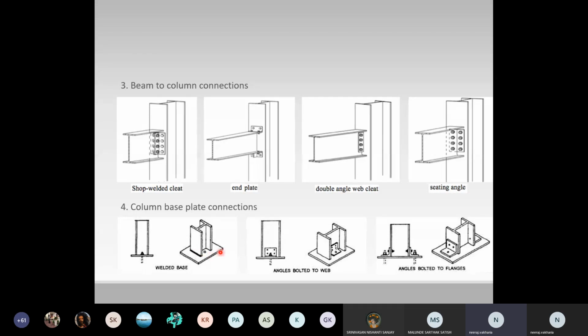Again, even the slightest difference in the level of this plate, the structure might tilt as you go above. The further connections, which are pre-designed digitally, might not be able to get executed on site if there is the slightest difference in the level or even in the distance of the connections. So that has to be considered, and it has to be properly leveled with the grouting.